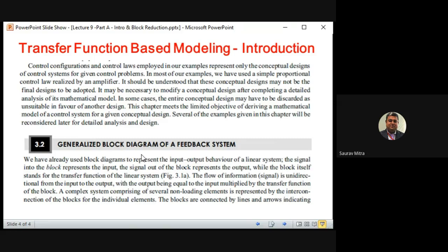We have to bring all the things together and find a transfer function T(s) = Y(s)/X(s) or C(s)/R(s). So from a big block diagram to a small transfer function, which captures the whole system model into one equation of two polynomials, numerator and denominator, in the domain s. This is the job of block diagram reduction.